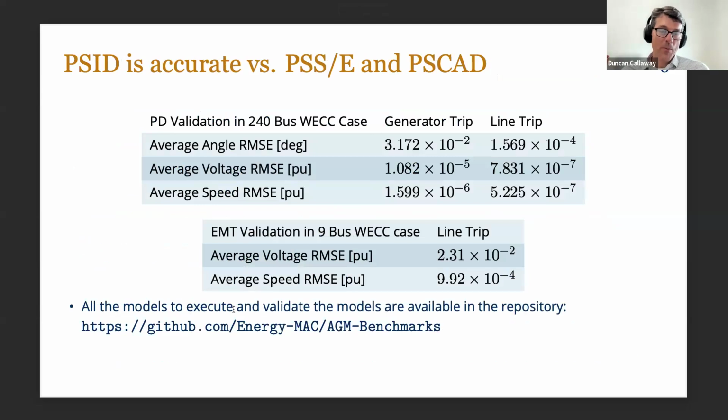So let's talk a little bit more, before I start talking about numerical integration, about accuracy. We've done a tremendous amount of benchmarking of PSID against commercial tools like PSSE, which is a phasor domain simulation tool, and PSCAD, which is an EMT simulation tool. And here are some examples of validation where we're reporting the root mean squared error between PSID simulations and either a phasor domain simulation, which is in the top table, or an EMT simulation in PSCAD, which is in the bottom table.